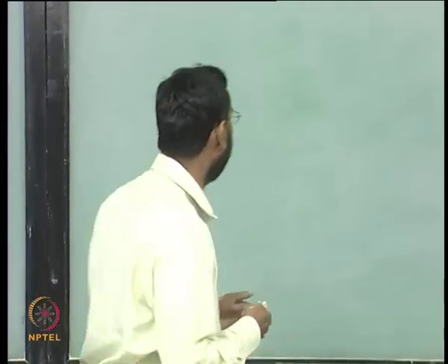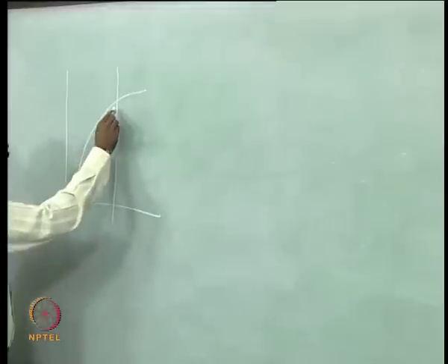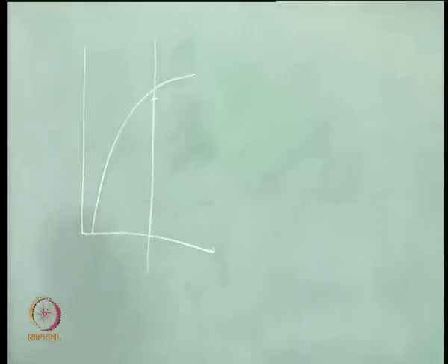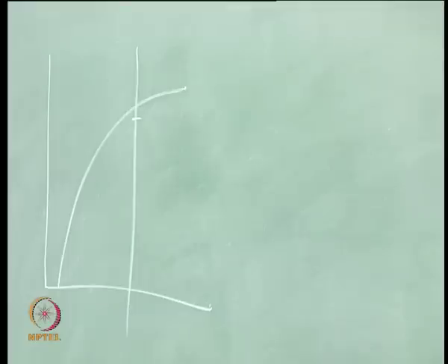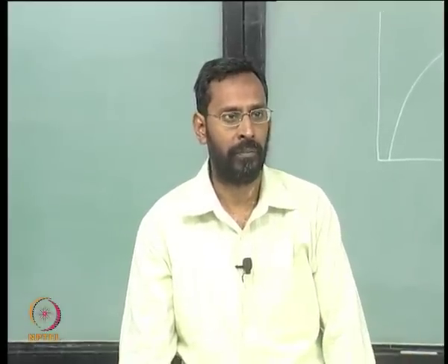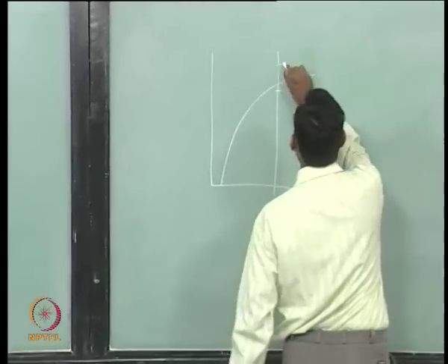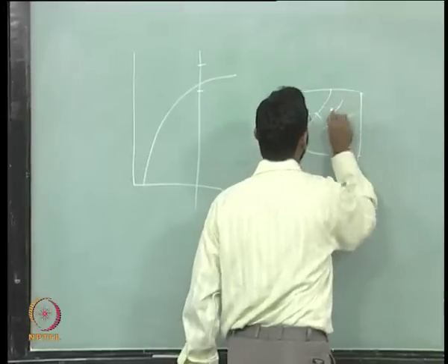If you consider any alloy, if the precipitation is taking place at that temperature, we already said that if you are just below the solvus line, you can easily have the nucleation of the second phase happening at the grain boundaries. So, if you consider an alloy at that particular condition, the alloy would be something like this, let us say alpha phase.